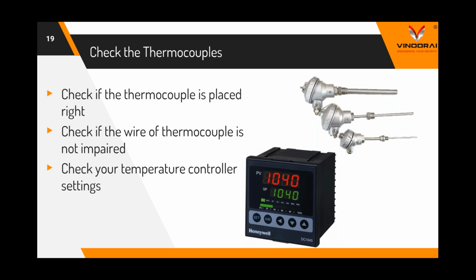Also, one very important thing, mostly when you change your thermocouple or you're using a new temperature controller, make sure that the settings of your temperature controller are complying with your thermocouple, because finally the temperature controller which you are using and a proper setting will help you gain good efficiency. Like the hysteresis temperature must be optimized to get good fuel efficiency. Also, deposit on the thermocouple probe can lead to false readings or readings with lag. So cleaning the thermocouple probe and the end regularly will give you a good result.